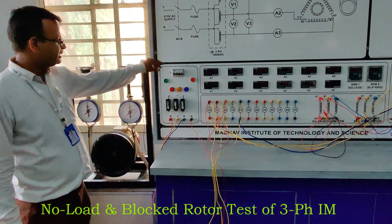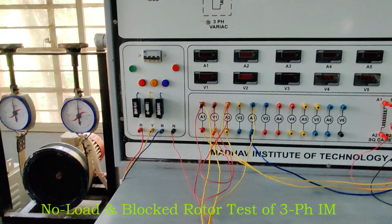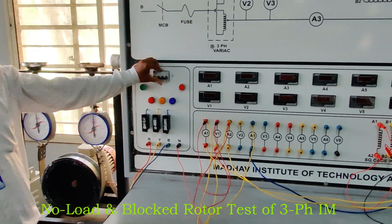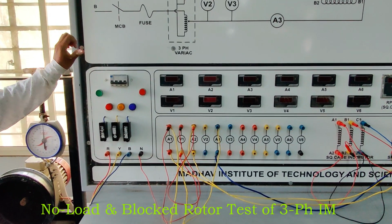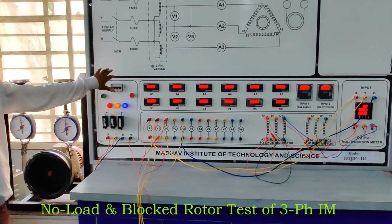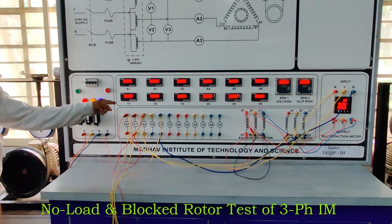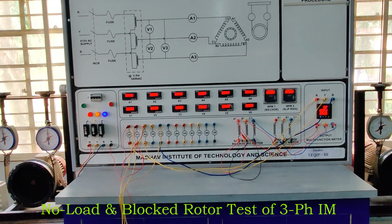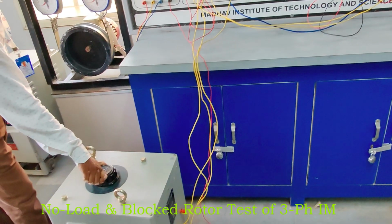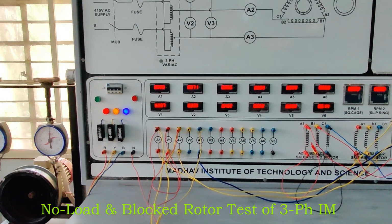Now take the supply, switch on the MCB, and with the help of the auto transformer gradually increase the voltage up to 415 volts. We start the switch and see deflections in all the meters. We measure A1, A2, A3 and the multifunction meter. Gradually increase the voltage and watch the V1 voltmeter.